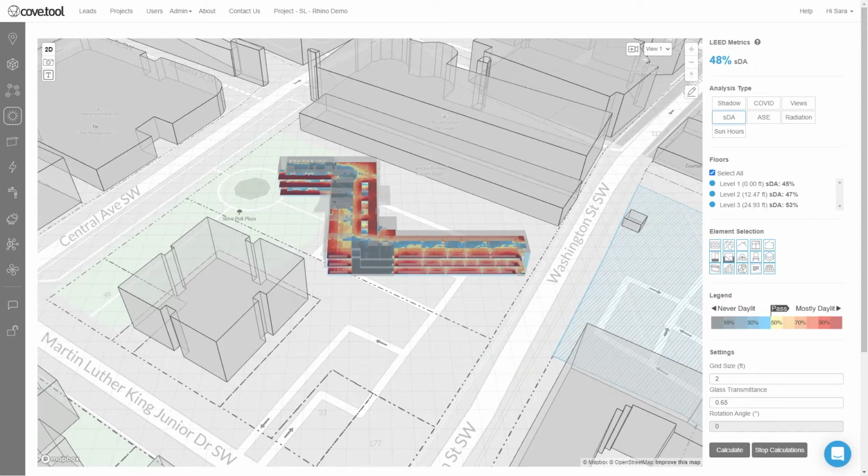Exterior walls are 35% reflectivity, and outside ground is 40%. This allows any user to construct a realistic simulation and avoids cheating the simulation with incorrect inputs. These are also the correct settings for a LEED daylight analysis by default. You can alter the analysis settings to change visual transmittance or edit the grid size. A larger grid will run faster, but provide lower resolution results.